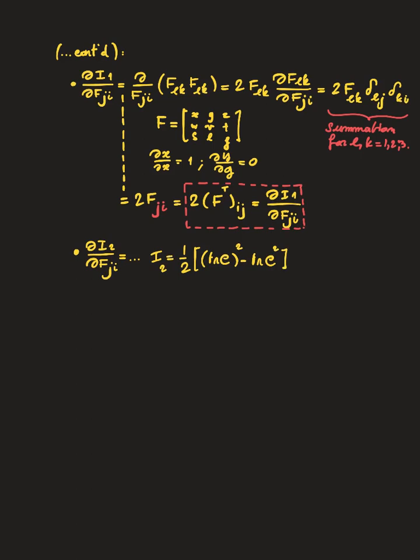Yes. So let's see how we express this expression here. Well, in fact, I just want you to remember that this is equal to 1/2 of, now the square of the trace of C, what is this guy? Well, the trace of C is I1. So this is nothing but I1 squared, right? And then I get minus the trace of C squared.